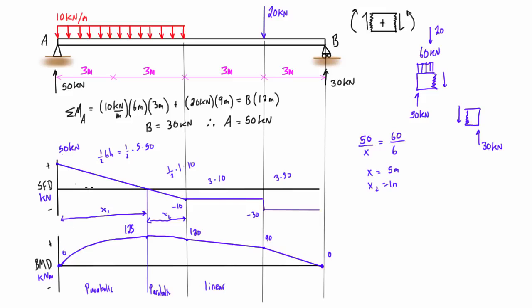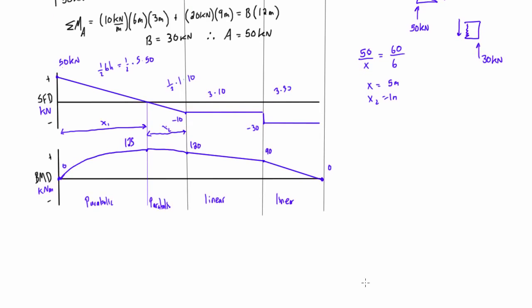So there we go. We got the shear force diagram with basically all of the critical points on there, and we also have the bending moment diagram, the general shape. We know where it's parabolic and we know where it's linear. And then we also get these key points every time it's switching into a new region. The one other thing that we can do, if you want, or if it's being asked of you, is draw the deflected shape.